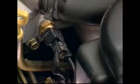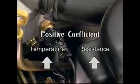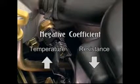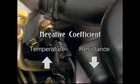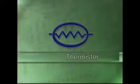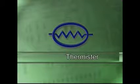Thermistors are variable resistors that change their resistance in response to temperature. Thermistors can either be positive coefficient, meaning they increase in resistance as temperature increases, or they can be negative coefficient, meaning they decrease in resistance as temperature increases. A thermistor is shown in the wiring diagrams as the symbol for a resistor enclosed in an oval.